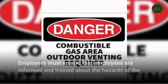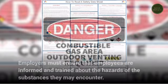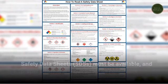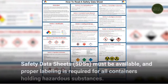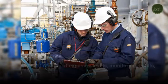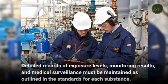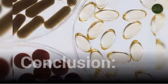Employers must ensure that employees are informed and trained about the hazards of the substances they may encounter. Safety data sheets, SDSs, must be available, and proper labeling is required for all containers holding hazardous substances. Detailed records of exposure levels, monitoring results, and medical surveillance must be maintained as outlined in the standards for each substance.